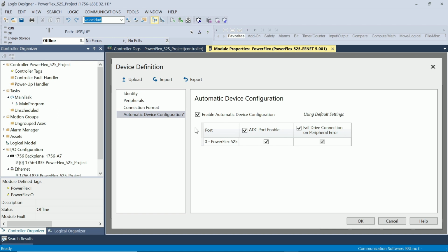All I'm going to do is with my Ethernet IP connection, we're going to be able to identify that the device is exactly the same as the previous one. And it's going to download all the information automatically. Okay? So that's the advantage for this tool. Now, of course, I recommend that you leave this enabled. Okay?